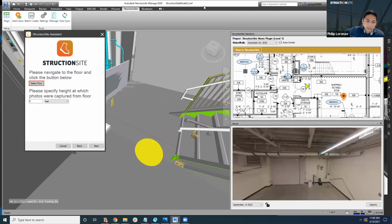Yeah, and there's another question. If a plan gets updated, which often happens, you don't have to realign it, as long as the updated drawing doesn't suddenly move or go into a different position. Typically it stays the same. It's revisioned and everything is aligned where it's supposed to be. Then the PDF file can be replaced. So that's automatic, that's no problem. And if you've synced the drawing from a cloud source where you typically slip sheet your drawings anyway, that gets automatically slip sheeted and shown in the Navisworks plugin.